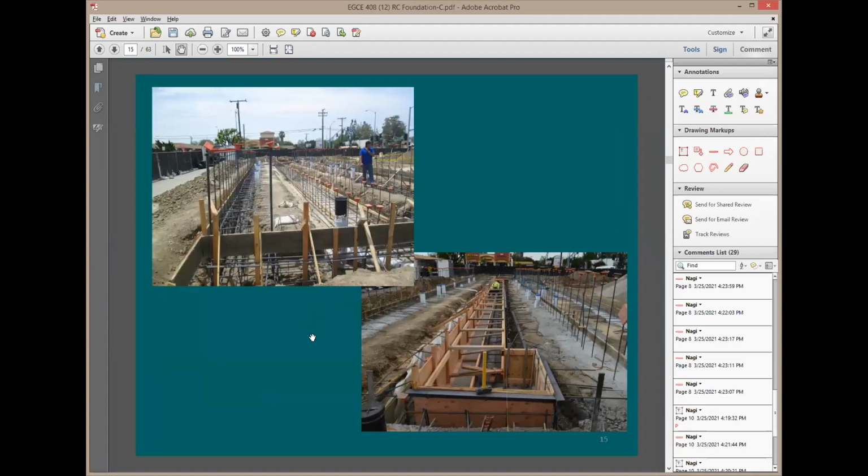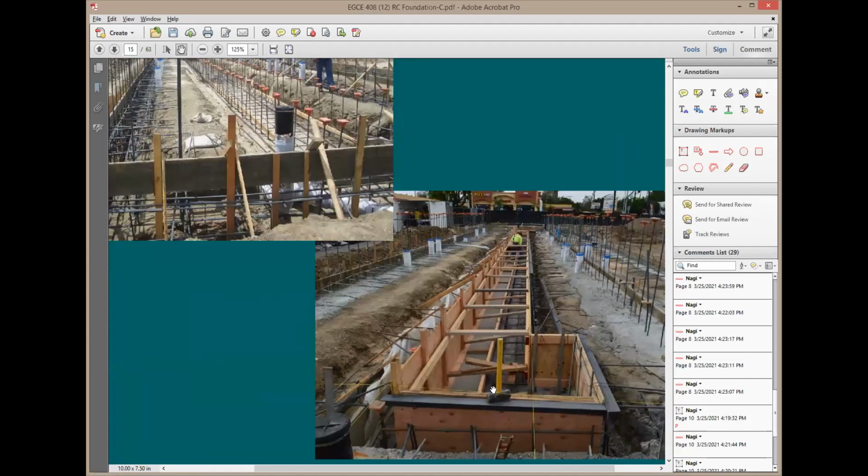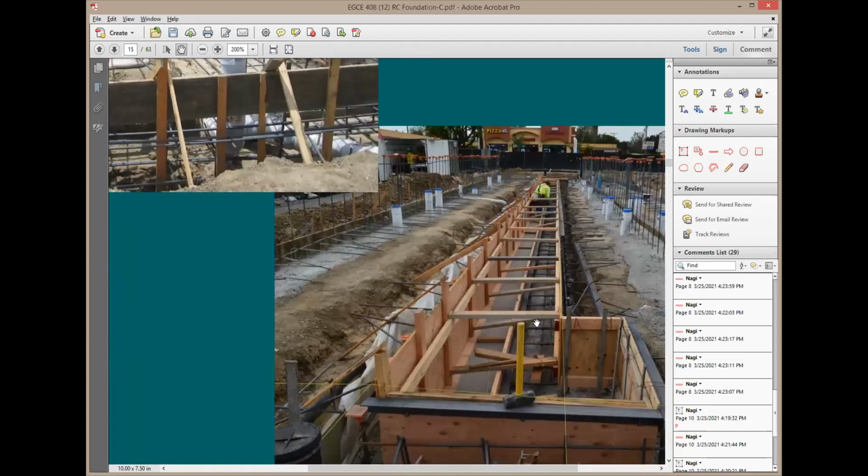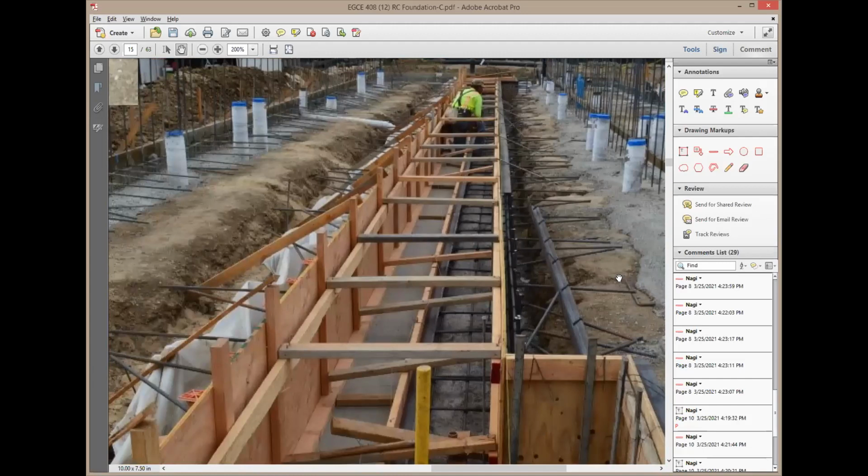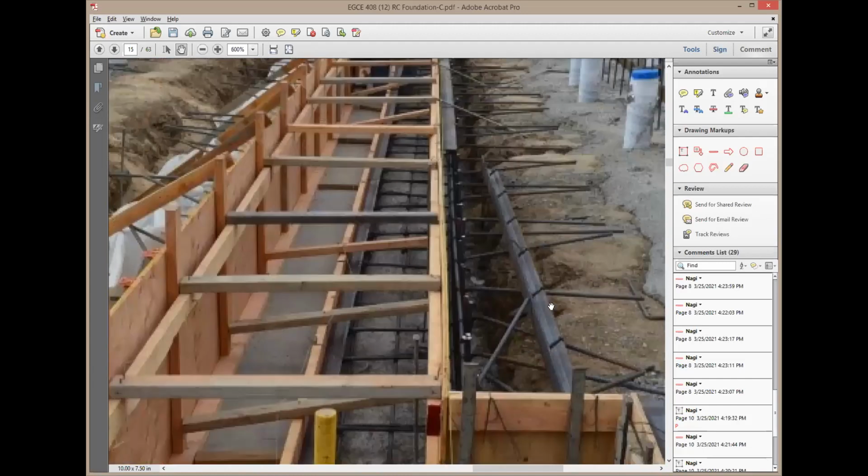That was another project. And look what happened here. We have formwork for the wall footing. And we have just done it from inside. How about from outside? Look, there's a soil. And you have all of the bars that stick out because you're gonna have concrete slab on grade on the top. So you'd connect them to each other.